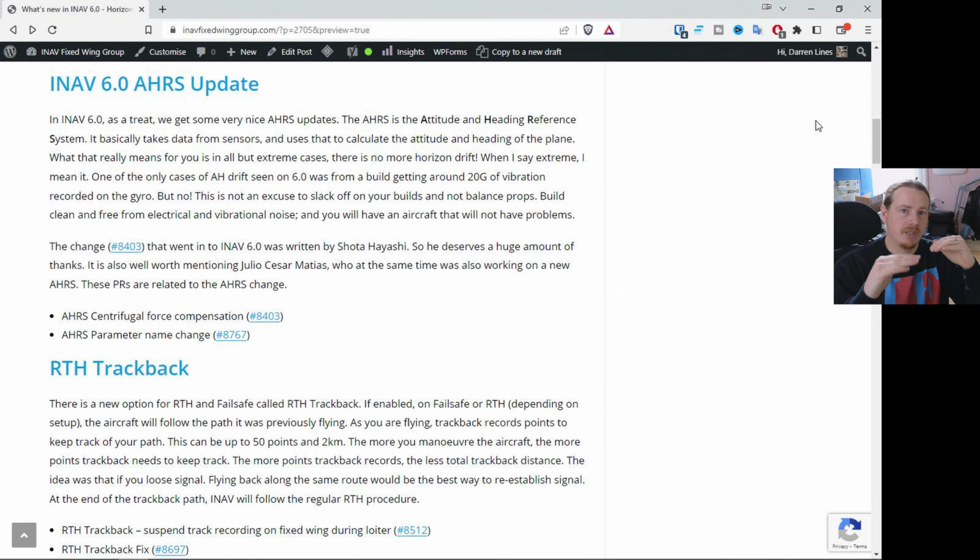The actual artificial horizon is used to calculate anything related to your flights. So if you have drift on it, it will affect everything from return to home, waypoint missions, even angle or horizon mode. They will all be affected by the artificial horizon being off. Acro, not so much, and manual definitely wasn't affected. But if you're flying a multi-rotor, for example, you don't have manual. So if you're flying in acro, you probably didn't notice, but if you're doing stuff like cruising and long range, it still can affect you.